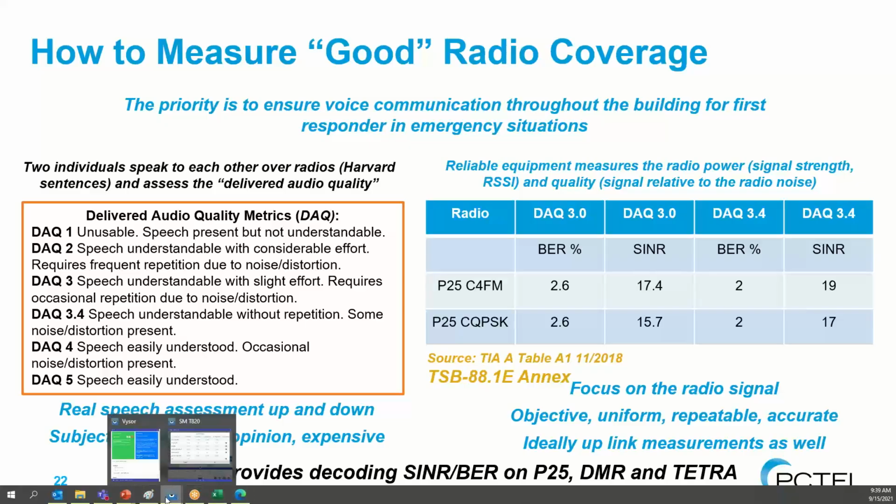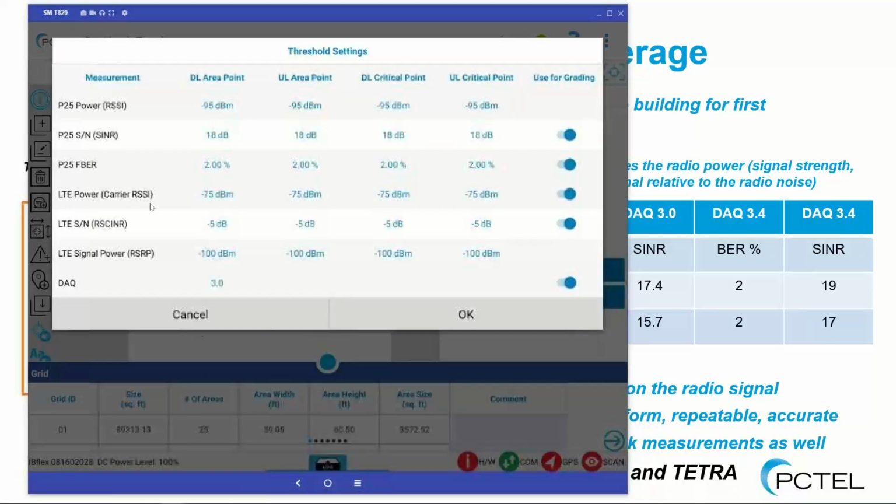Okay. Got you. For LTE, the default measurements are probably not very good. I don't really worry about carrier or RSSI. I think the default measurement for LTE SINR is at +10, and that's really, really bad. I mean, a +10 SINR is achievable in probably a lab environment. You're not going to see a lot of that in the outdoor network unless you're standing right next to an antenna.